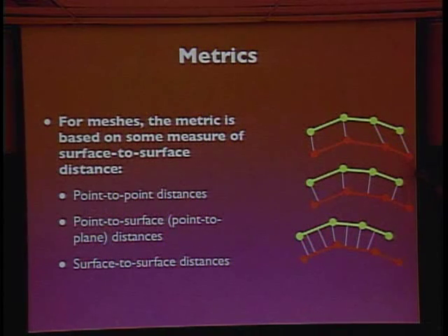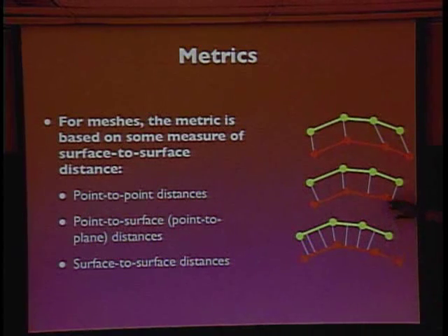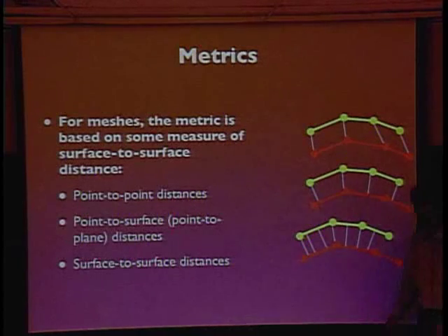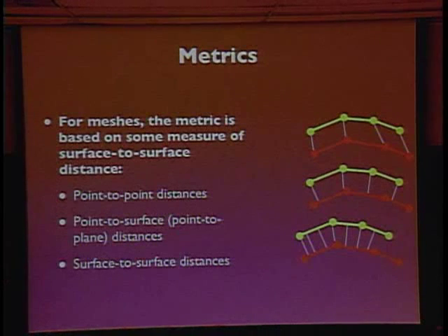What you have to do is for each point, cast a ray in some direction, and then for every face on the red surface, determine how or if that ray intersects that plane. And furthermore, you need to be smart about the shape of the object, because if this red surface wraps around and the ray intersects with a plane that is way down here, you want to detect the fact that this one is closer. So you have to do more or less computer graphics type calculations that ray casters use to calculate whether a ray of light has intersected with a plane on an object in the real world.